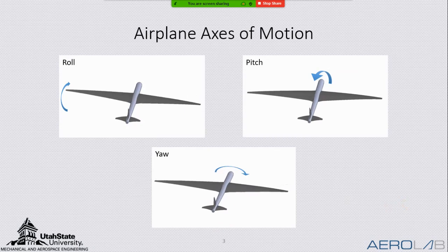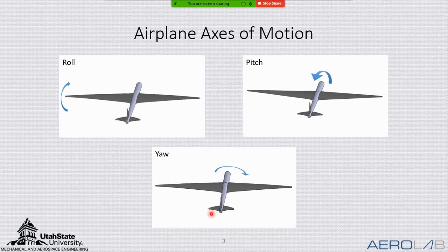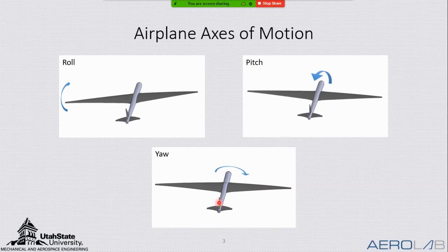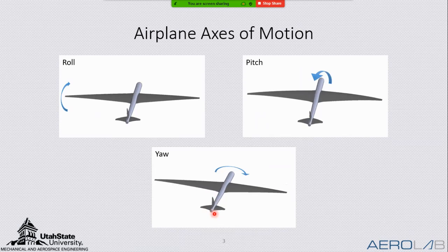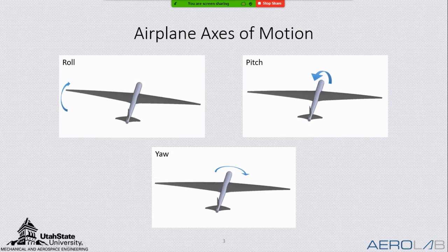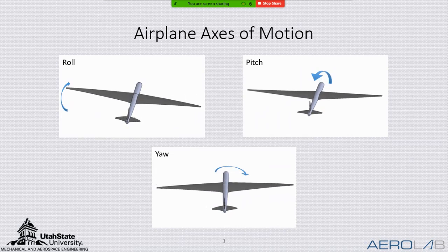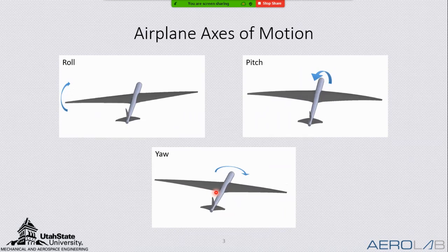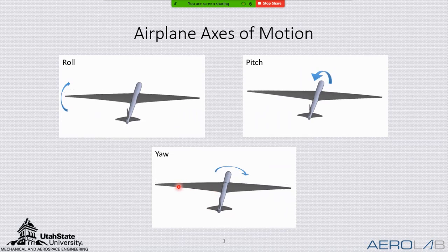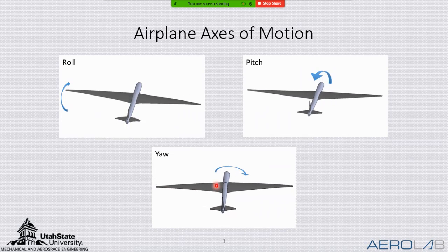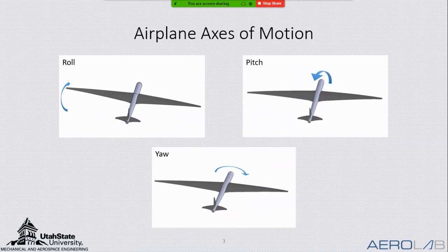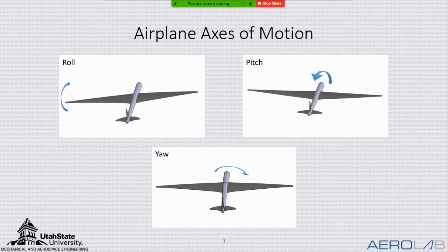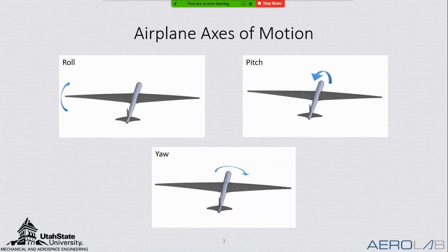And so we can get rid of those surfaces, but, in an oversimplified statement, we generally use this rudder, this vertical surface here, to control yaw on the aircraft. How do we control yaw on an aircraft if we don't have that vertical surface? One potential solution is to have multiple control surfaces along the wing, each of which are actuated differently in order to produce a yawing moment on the aircraft.